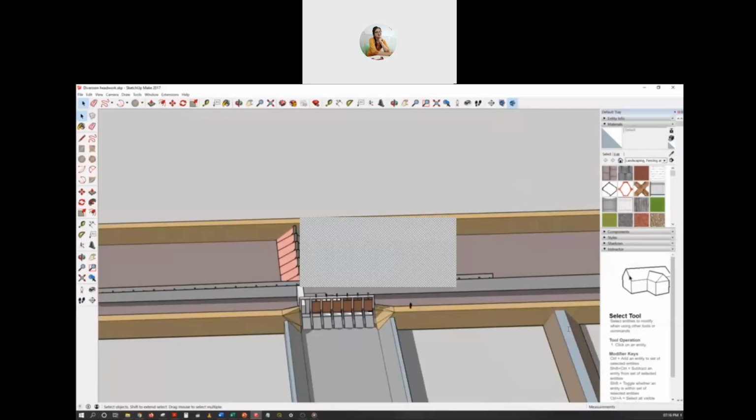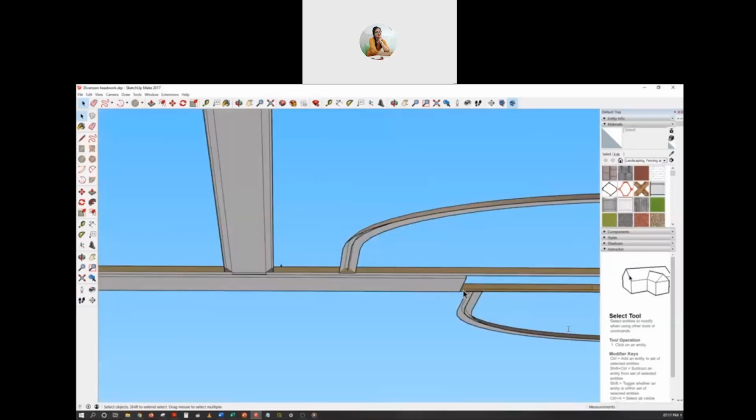So what we have done is we have provided an impervious floor so that water cannot enter in this portion. Water has to enter here in this location, and it has to flow under the ground, under the floor, and through this it can be released at this portion to the downstream. That means we have increased the flow path. To further increase the length of the flow path, what we can do is provide some sheet piles here.